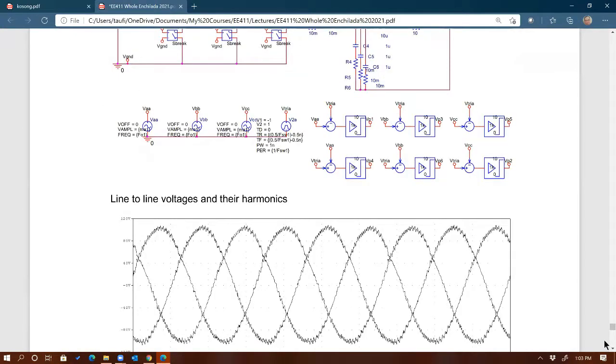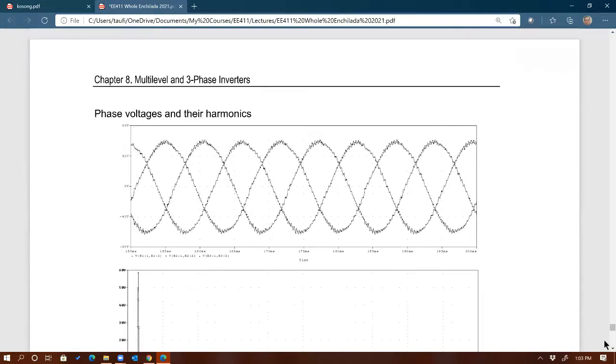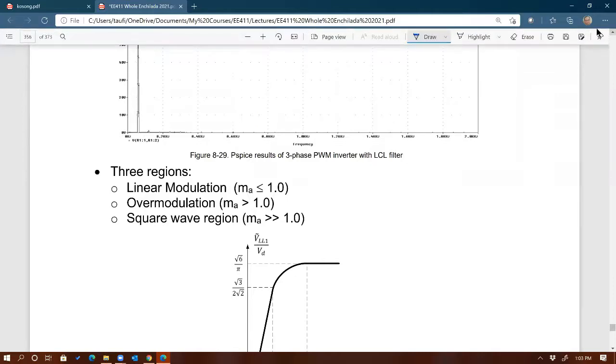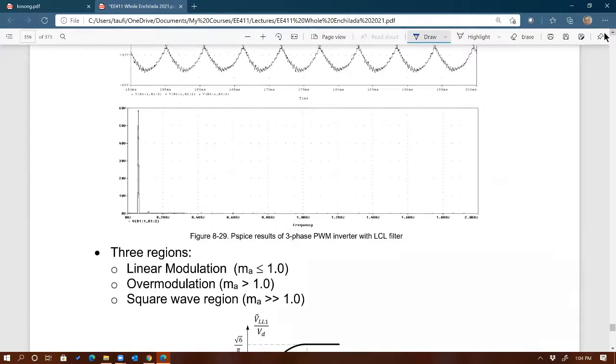So that's why, because of those many switching losses, switching actions, the PWM inverter is not being used for utility scale applications. Right? They use medium. They're being used for medium level, such as solar panels, but beyond that, it's too much loss to use PWM. Too much switching loss. Okay.